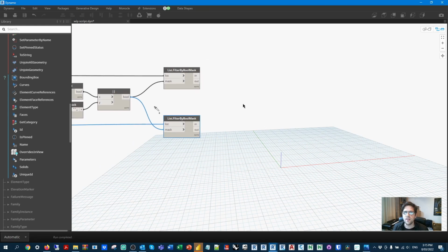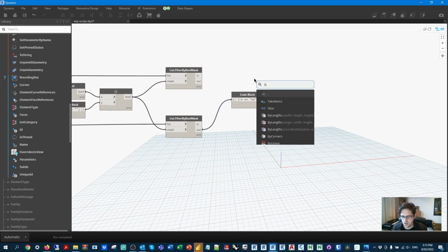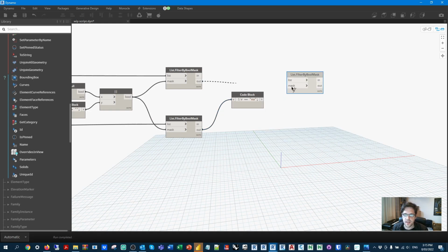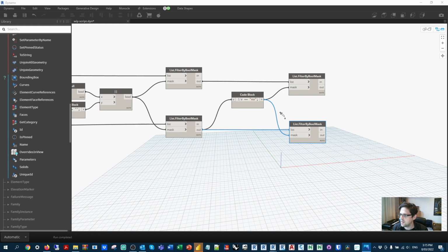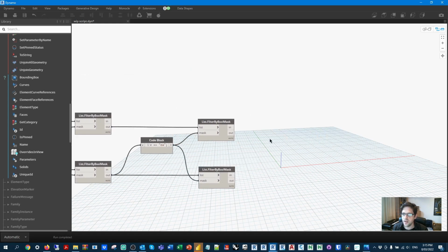I'm now going to separate the results based on whether they are of an each rate, because in this case, the each rate will just be the cost of the object. So I want to, in this case, make sure that I get that parameter properly. So I'm also going to check for does the value equal each? And from my out list of cost rates, we're going to be hunting down the objects that are costed on an each basis. And then also filtering, in this case, the out list, so that we can take our data using two pathways. So I'm also filtering my values. And let's just firstly deal with our each values.